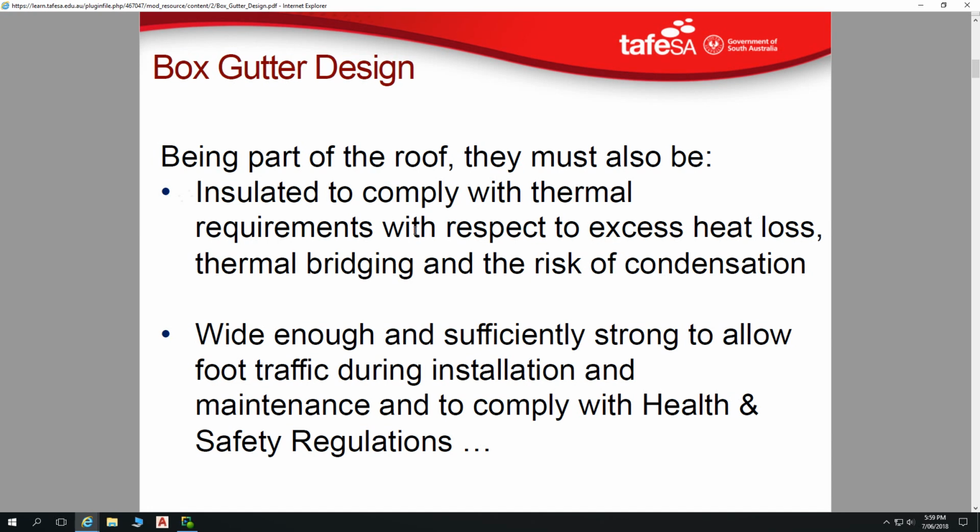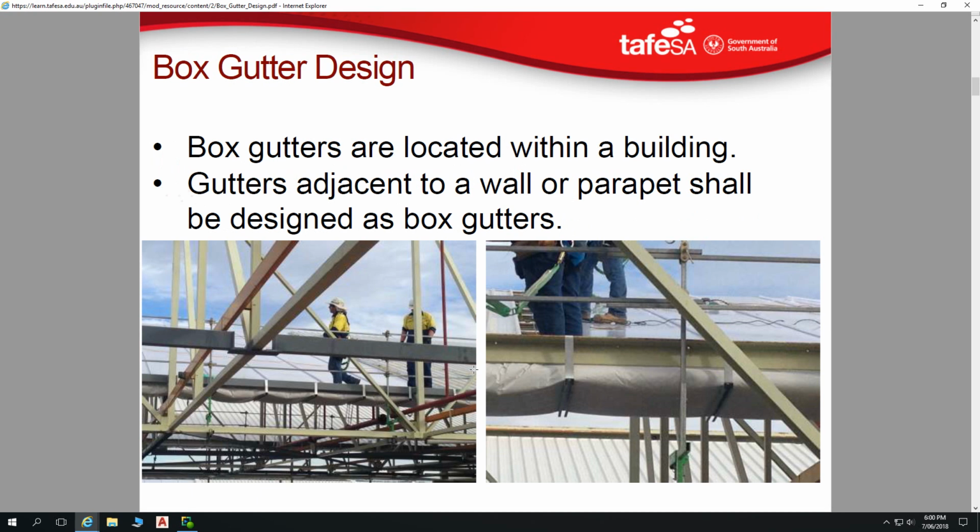In cases, not all cases, but wide enough and sufficiently strong to allow foot traffic during installation and maintenance, to comply with health and safety regulations. So some box gutters are designed to be trafficable, others are not designed to be trafficable, but they should be designed to be strong enough at least to install.